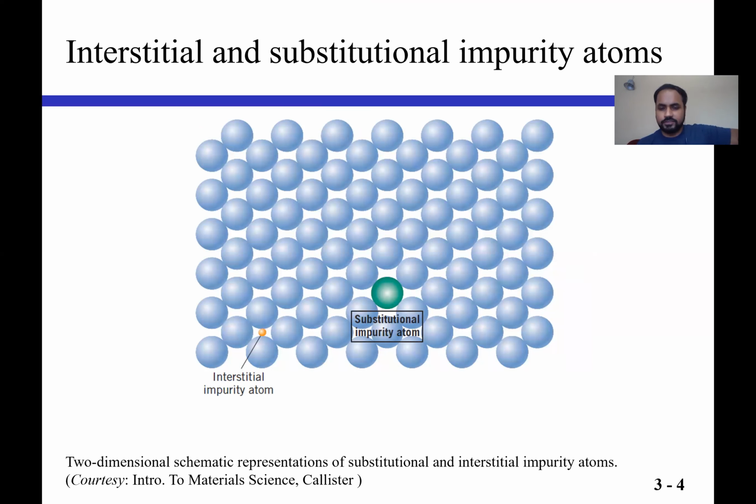And this is the strengthening that I was talking about. You can have strengthening via interstitial or substitutional alloying addition. When we add carbon, the main alloying element in steel, it goes to the interstitial position in between the atoms and provides strengthening. But let's say you have stainless steel. Stainless steel becomes stainless because of the addition of chromium, and chromium is really big. So chromium goes to the substitutional site. That means it replaces one iron atom and sits in place of that atom, and that's how it provides different properties. But if you compare the strengthening behavior, carbon is going to provide a higher strengthening than chromium in the case of steel.